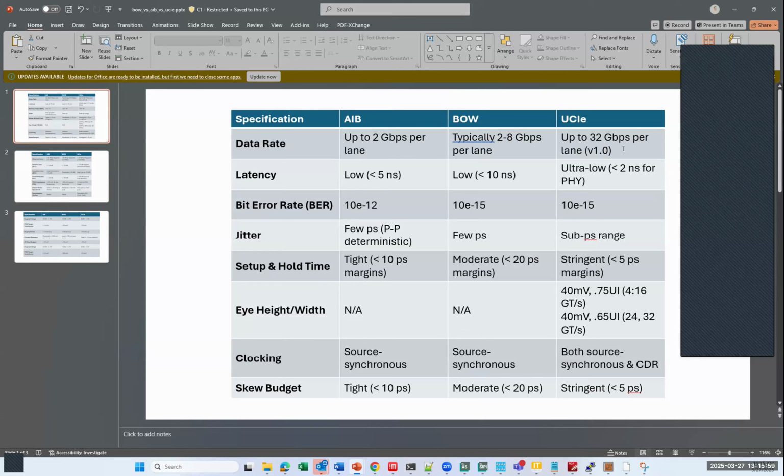What I can say, looking at DDR systems, for example, is that you can run those modes in off-center data rates. It's just not necessarily guaranteed. Let's say if you've got a Micron vendor model, they will guarantee the operations at JEDEC defined data rates. If you decide to run off speed, you have to go in and adjust all of the controller timings and all of the margins, because those are all based on those speed bins per the spec. So if you want to run at a lower data rate, that's okay. You just have to go in and, whatever analysis engine you're running, those configuration parameters would have to be changed.